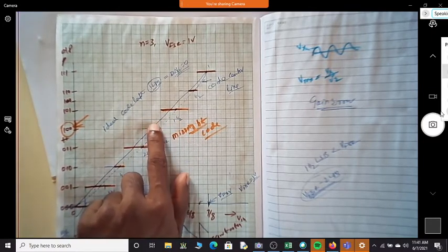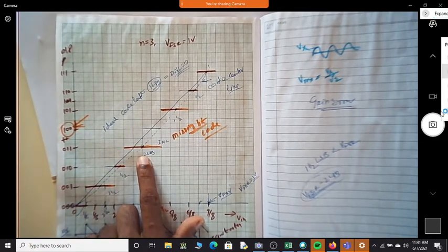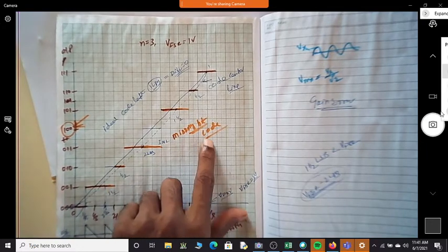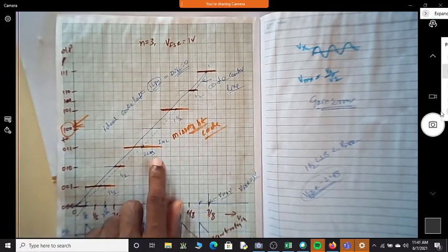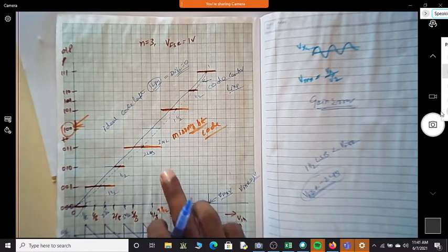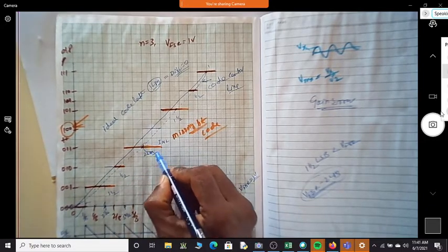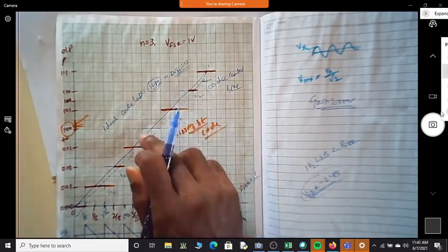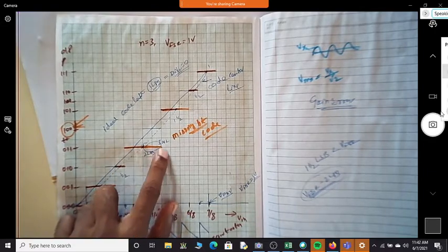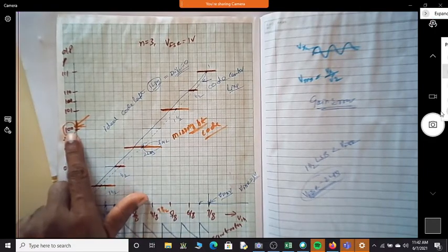You are not getting it because one of the DNL is more than 1 LSB. You will have a missing code if the DNL is more than or equal to 1 LSB, because this is actually the representation of the next code that is being represented by the previous code itself. Because of this error in your ADC, you are missing a code here.